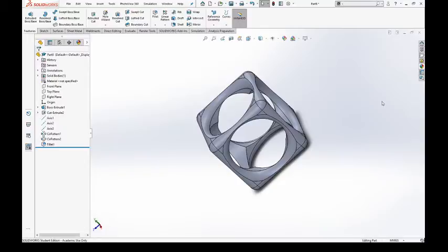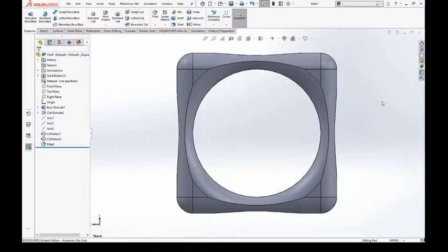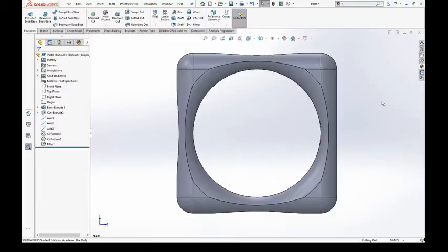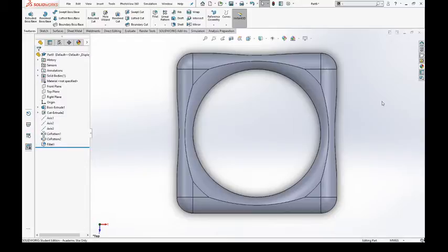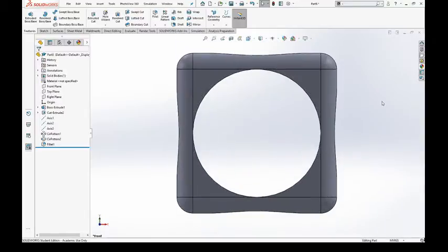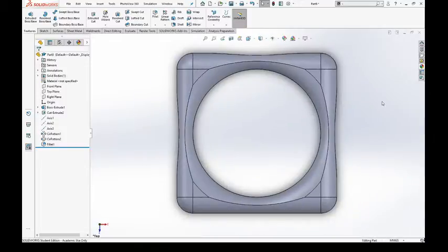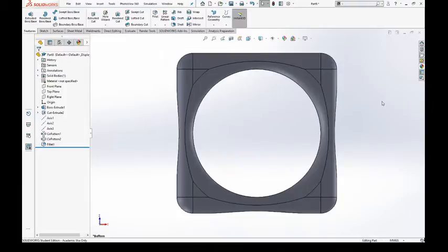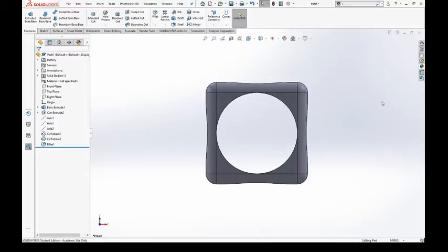You can also use the control button on your keyboard and the numbers 1 through to 8. So control 1 would look at a front view, 2 would look at the rear view, 3 would be a side view, as would 4, 5 would be a top view, 6 would be a view from beneath. So go through it again. So front view, back view, left view, right view, top view is control and 5, bottom view control and 6, control and 7 is the isometric, and control 8 will be the normal 2 view.